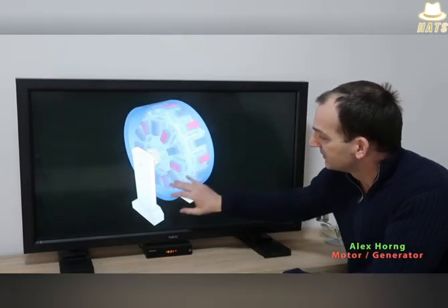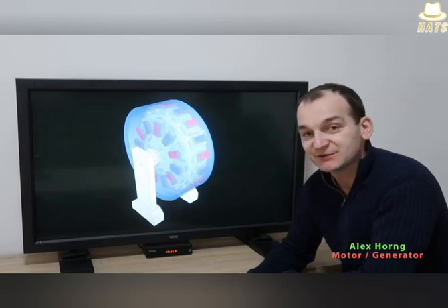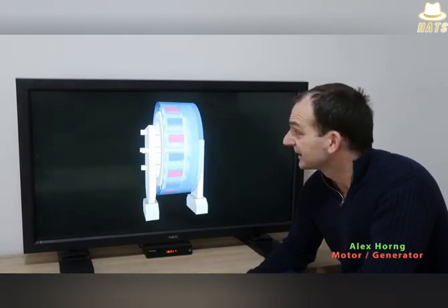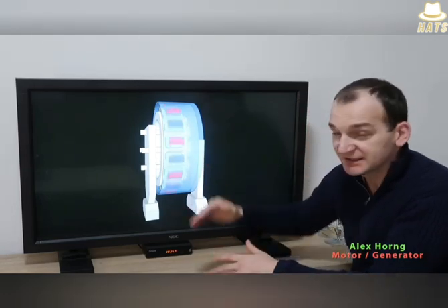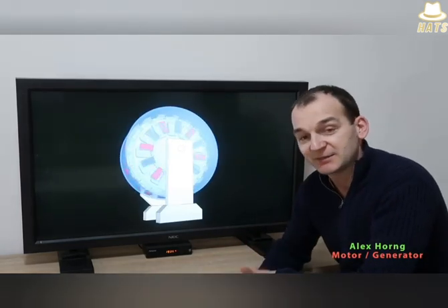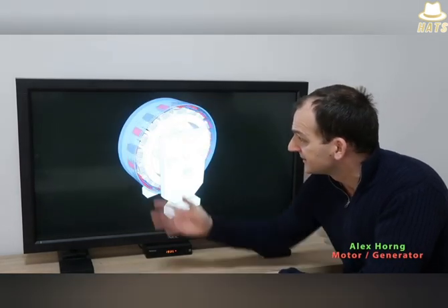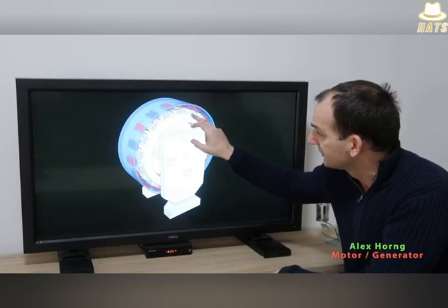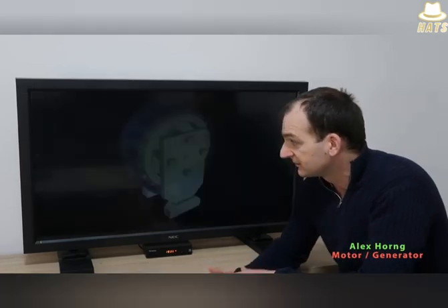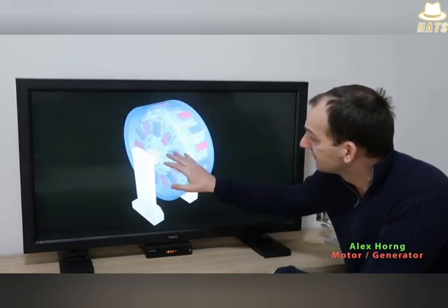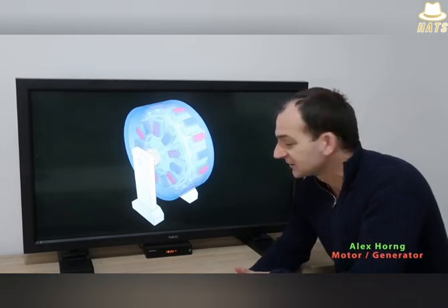Okay, so this is the deal. Now you can see that this blue outside which is spinning is the rotor, and on the rotor are somehow fixed those permanent magnets. Each second one is with a different magnetic pole. So it's set in this way. And why is it so? On this coil, on the stators, you see them, many of them, they are arranged each differently so that we can get alternating current output on it. Let's say the primary coil and the secondary coil.